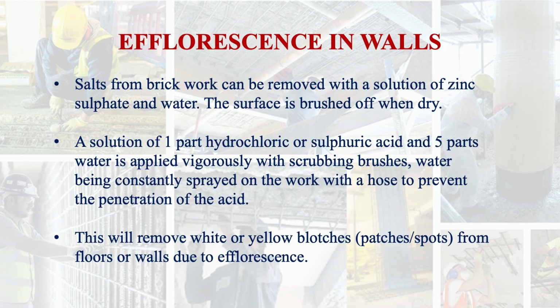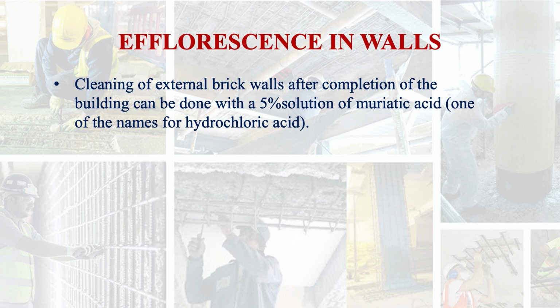This will remove white or yellow blotches, means the patches or the spots from floors or walls due to efflorescence. Cleaning of external brick walls after completion of the building can be done with a 5% solution of muriatic acid. Muriatic acid is another name for hydrochloric acid.